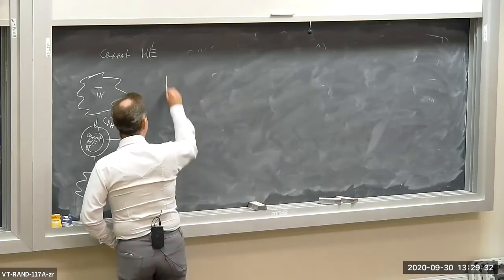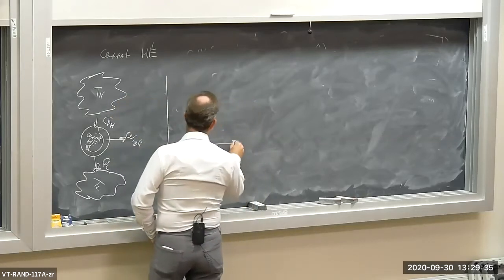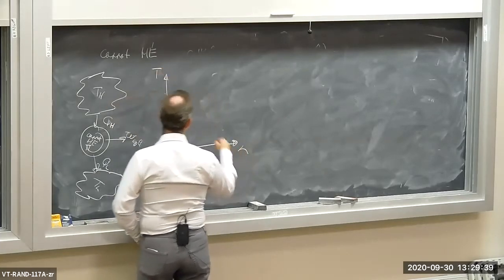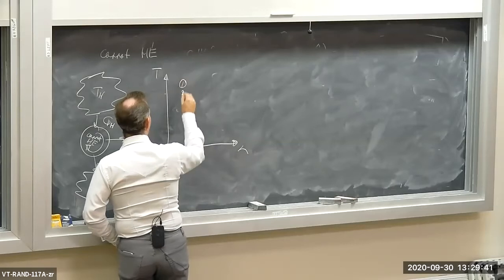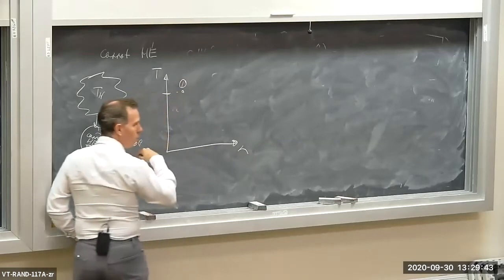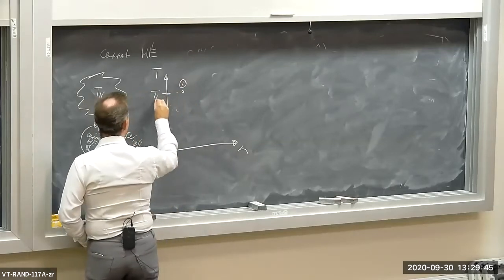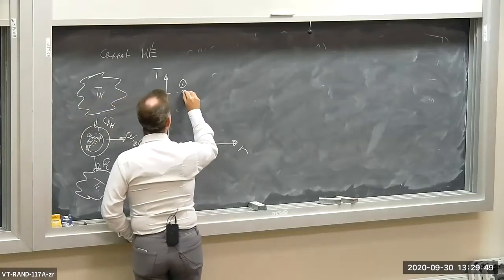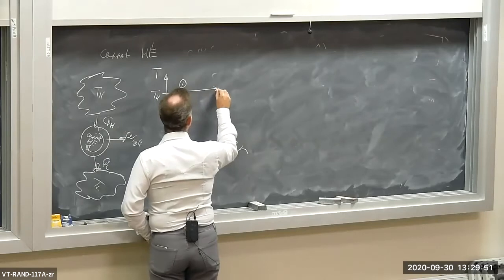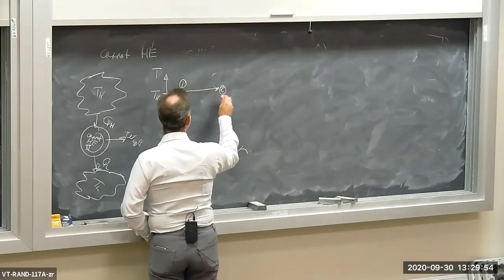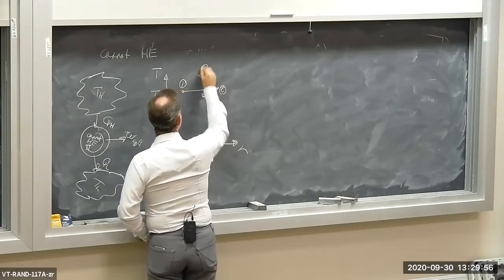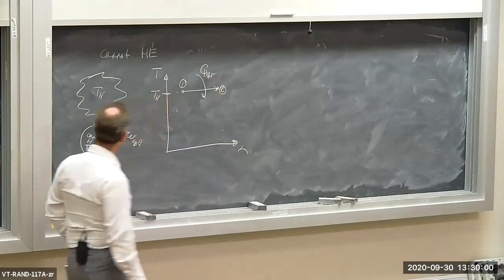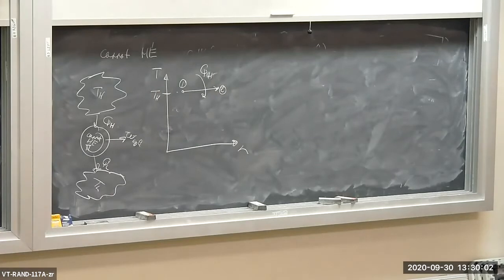The TV diagram, as you recall, for the Carnot cycle: we start at state 1, which is the working fluid at a temperature T high, at the minimum volume, and then we expand it to state 2 isothermally. This is where the heat transfer is being performed from the high temperature reservoir at TH.